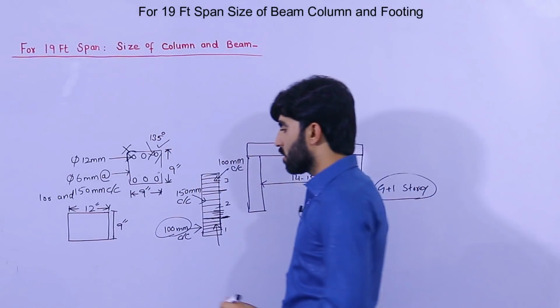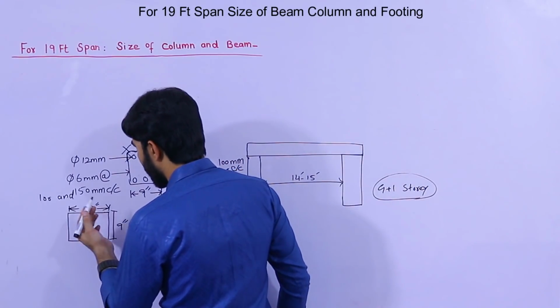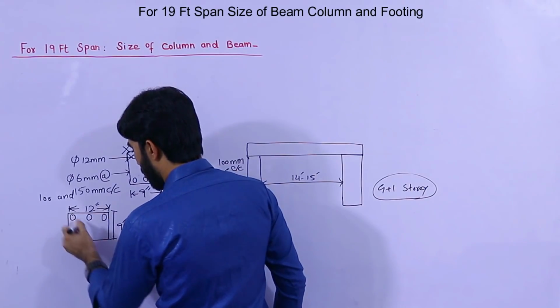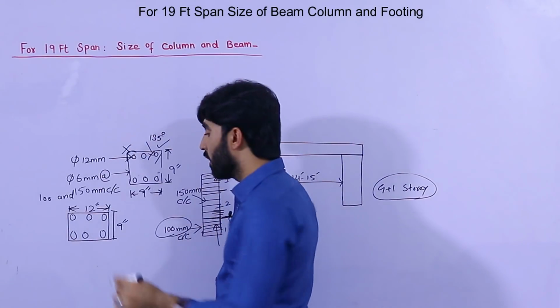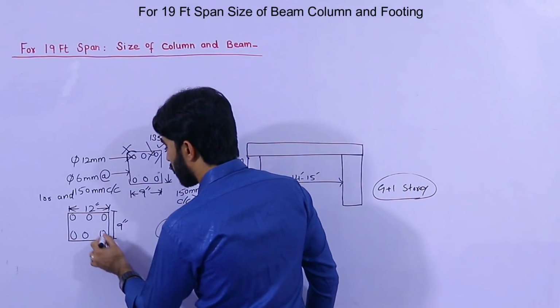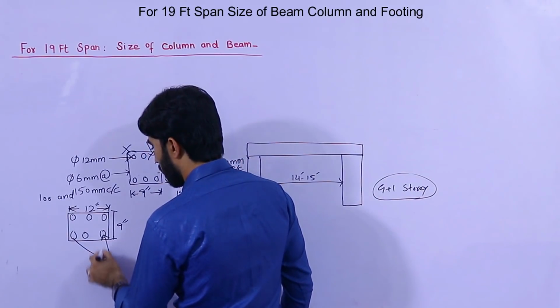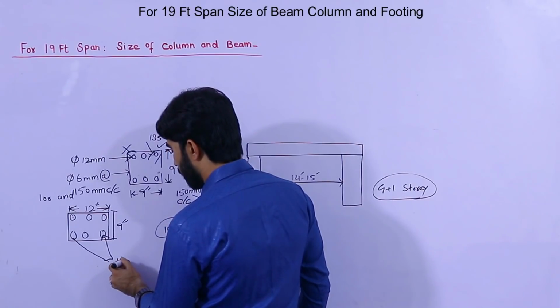And in this case, you can use also 6 steel rods. It's okay, 6 steel rods should be used. So these 4 steel rods, the corner 4 steel rods, this one as well as this one, also these two, this dia should be 16 mm.